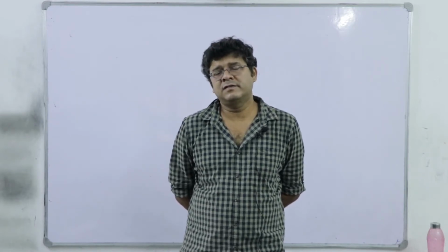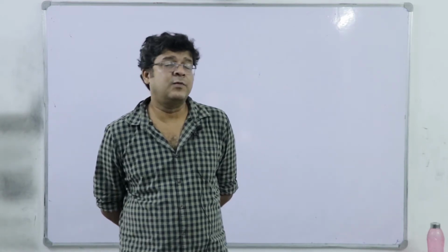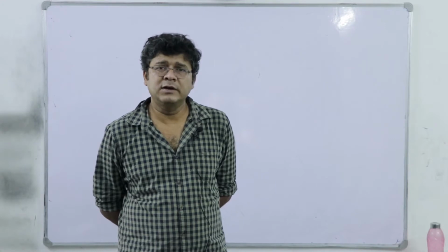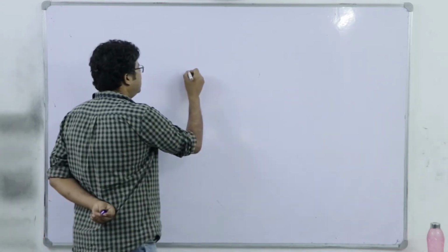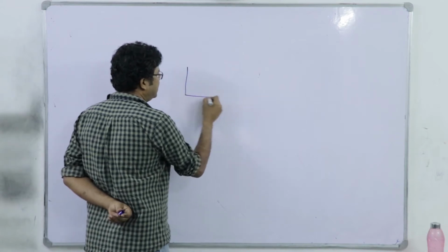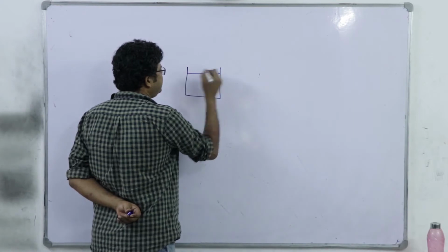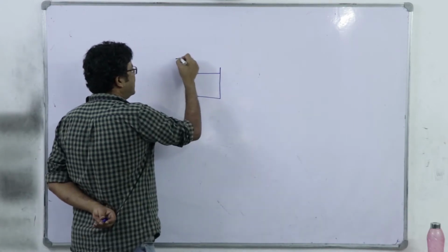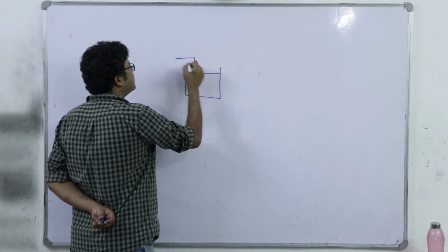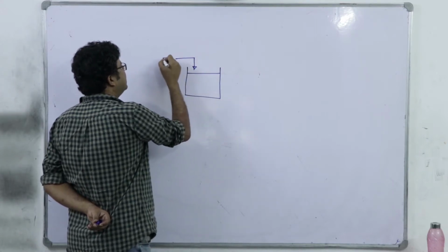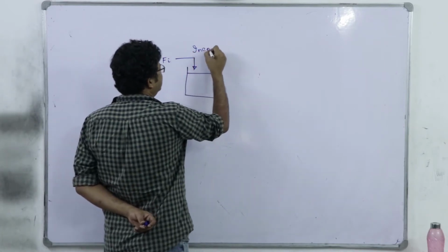And so let's start by understanding what are the input and output to the device, right. Very simple. We will start with a very simple process equipment. Let's think it is a storage tank, right. It's a liquid storage tank. We have an inflow. Let's say the inflow rate is Fi, and it is an incompressible liquid.